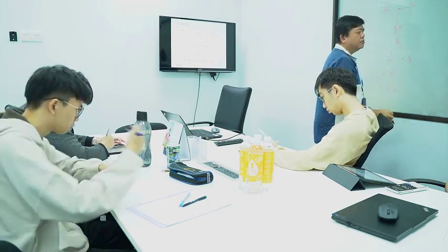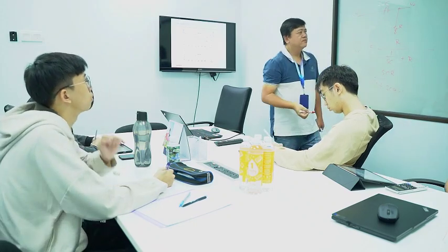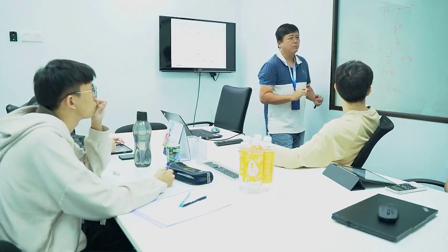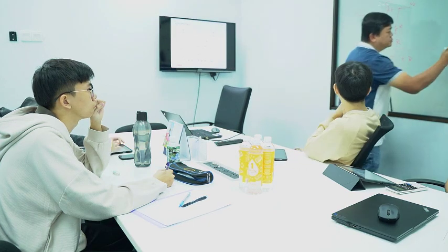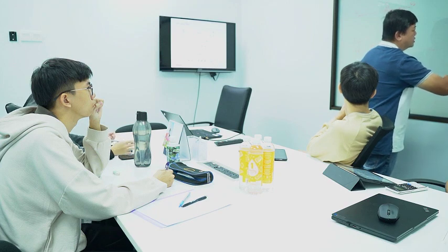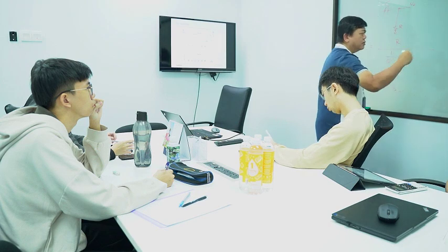What do I mean by infinite zero? Infinite zero means you have a zero with a slope of plus 20 dB per decade. It just simply goes up, and the slope is plus 20 dB per decade. It just goes up until it meets the pole frequency you set here.